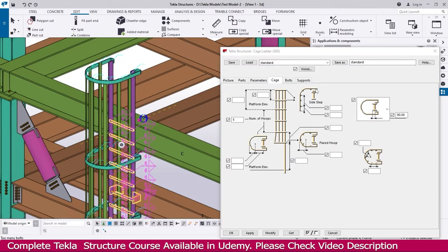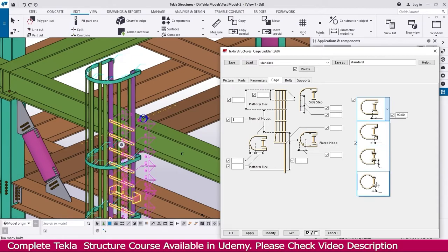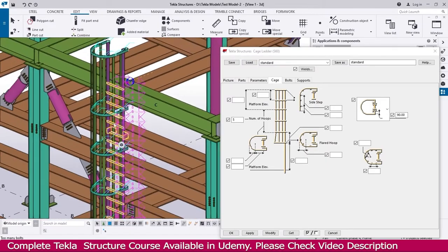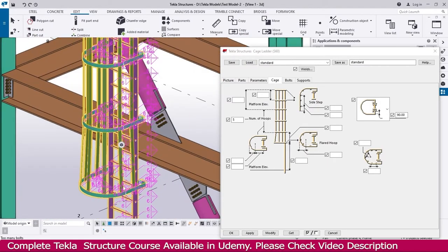In a similar way, you can control it if you use the side entry of the ladder. Before, I told you, if you are entering or exiting sideways, you can add the vertical bar using this distance. And if you go here, you will get a few things, and which type of hoops you are using depends on the hoop. You can select the distance and all, this straight distance, and here from this center how much it needs to exit this bottom hoop, you can decide here. See here, I just select this one, and the bottom hoop only needs some more distance.